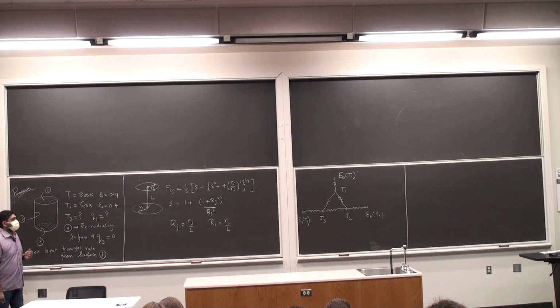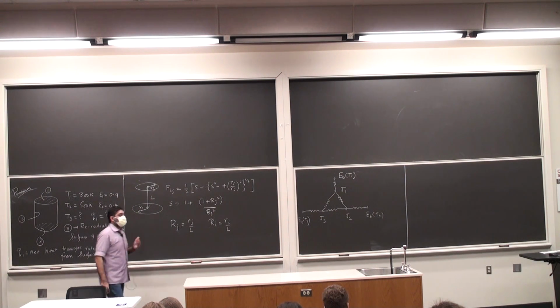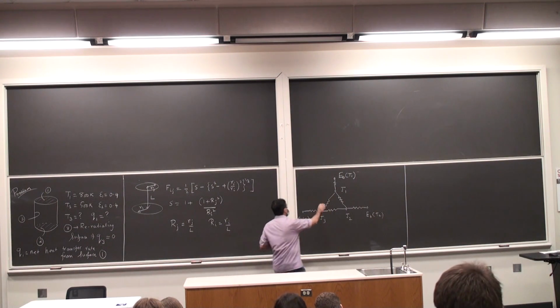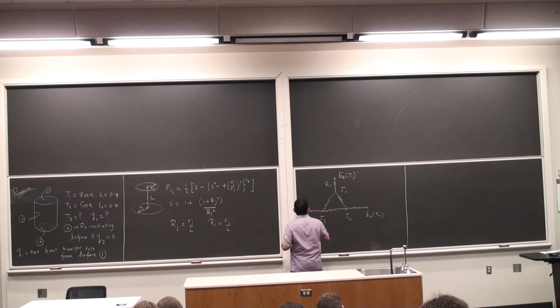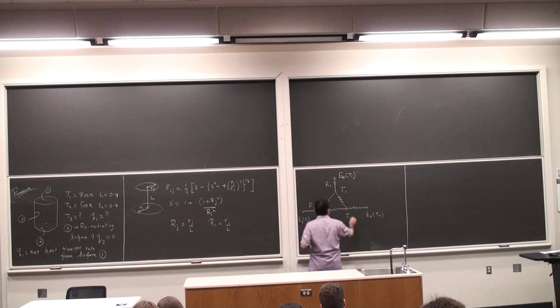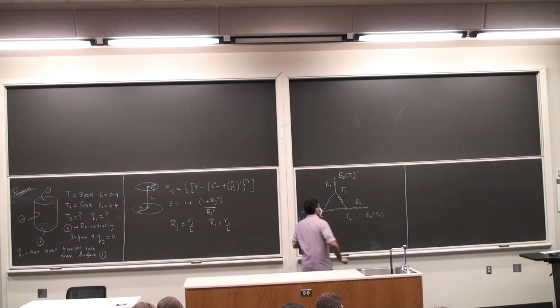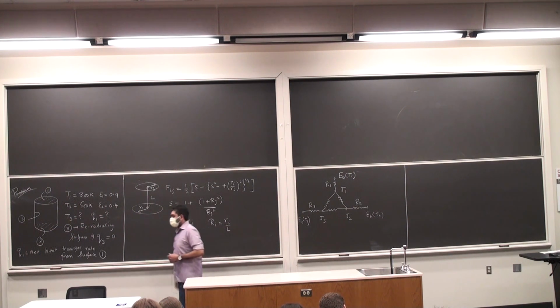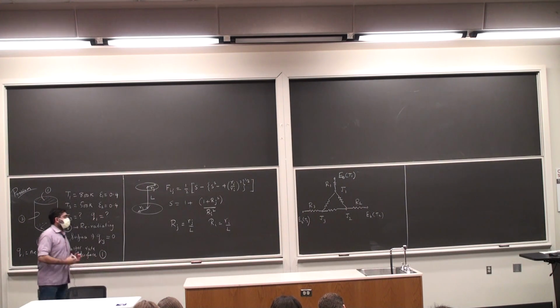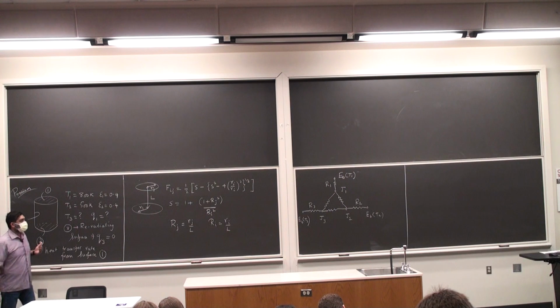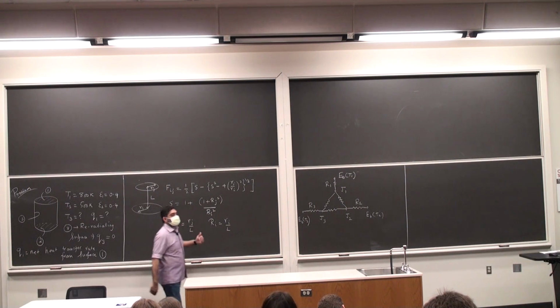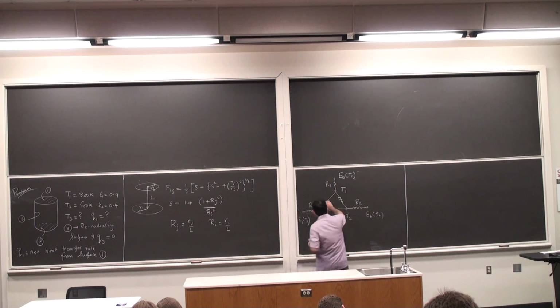The primary and the secondary nodes are joined by the surface resistance. So this is R1, R3, R2. These are the surface resistances. Then I have the geometric resistances which join all the secondary nodes. So between 1 and 3 I have R13 or R31.